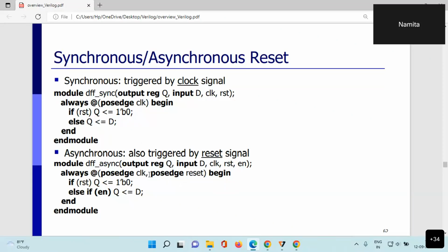Now here we can check why we are checking with posedge of reset. We could only write reset. Verilog supports this syntax, but the synthesis tool will not support it. If one trigger in the sensitivity list is edge triggered, the other one should also be edge triggered.